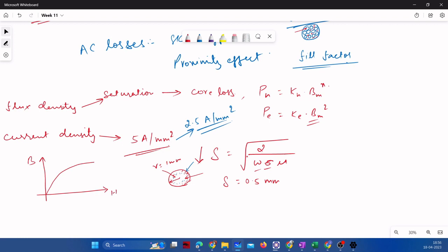You are correct, but in another way, it is possible that current density is not uniformly distributed. Some strands might not have whole area utilization in providing a certain amount of current. Then the current density distribution might be non-uniform, but the skin depth is always the same, no? Because the skin depth will not see any difference apart from these three factors.